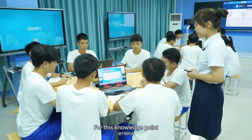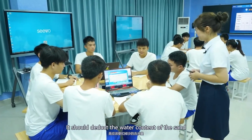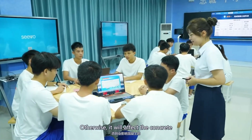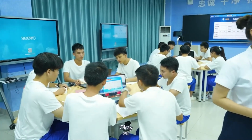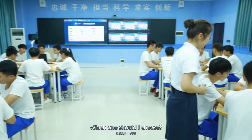For this knowledge point, I have covered the topic during the last class. It should deduct the water content of the sand, otherwise it will affect the concrete. You can review it again. Okay, you see, I said that we should subtract such weight. There are 3 options here. Which one should I choose?